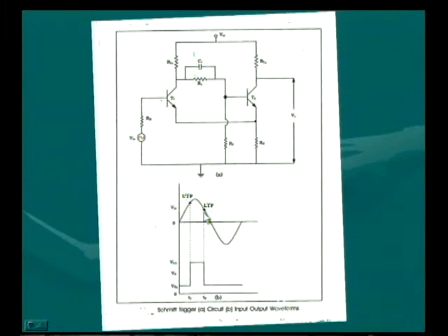So this transition is called the lower triggering point. Thereby the two finite values of the amplitude of input voltage will decide how the output of the Schmitt trigger is going to change from on to off and once again to on. The rate at which it happens will be decided by the amplitude of the input signal.